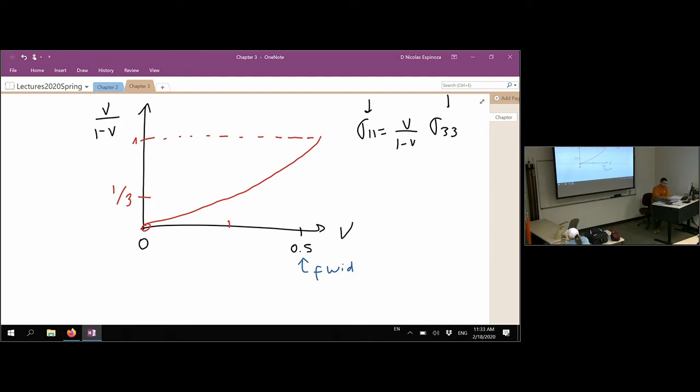However, for all other solids, and what will happen to most rocks that have a Poisson ratio far from 0.5, the horizontal stress with no horizontal strain is just going to be a fraction of the effective vertical stress. So it's not going to be pushing with the same weight that the rocks have in vertical directions. And that's a property of the solid that we said before, that it can resist a shear stress or a differential stress, so it can bear a load much higher in vertical stress than in horizontal stress, and still is going to be fine.